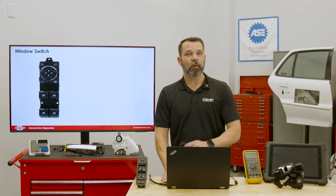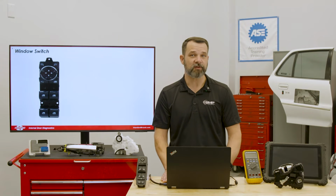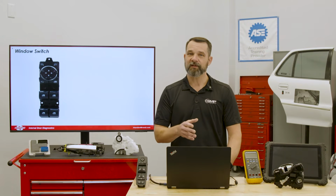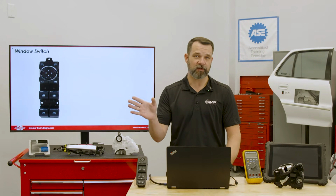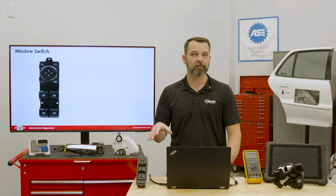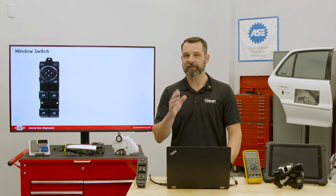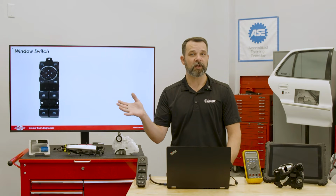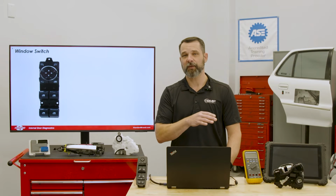But they can work in a very simple way or a more complex way, depending on the vehicle and the features. Right? They can either be a simple mechanical switch set, or in some cases, they're actually a smart module that sends the commands digitally across the network. And on modern cars, pressing the switch, remember this, doesn't directly power the motor. Instead, it just sends the request to either the, again, body control module or the door control module, which is then going to energize the motor, right?